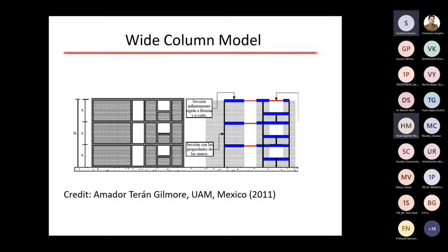Because the parapet portion of the wall below the opening is also rigid, if you want a more precise design or simulation of the behavior, then it is needed to simulate the behavior of this parapet as well. But it is not necessary.